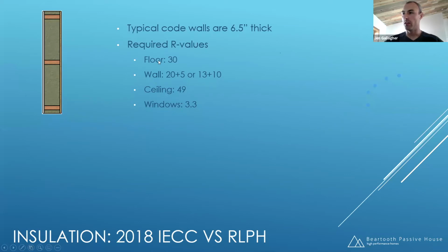Thing to keep in mind on the floor, the wall, and the ceiling, that is just the nominal R value of whatever insulation you're using. It's not the true calculated R value when you include studs and all of that kind of thing.